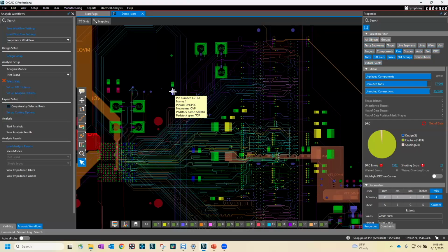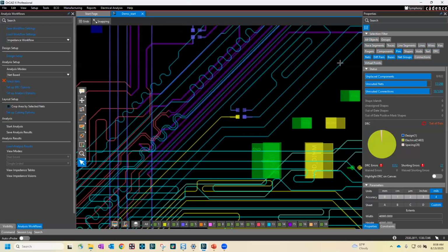All these analysis engines use an integrated, we call it a 2.5D field solver. It's a patented field solver we have that will look at a PCB. And if you have a situation like this that has a long trace running over a solid reference ground plane, it's going to model that using a 2.5D solver. So it's accurate because there's no reason to go full 3D, because it's not really a 3D problem.